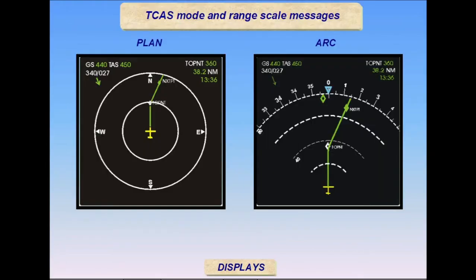When a TCAS message is present with the plan mode selected, a TCAS change mode message is displayed. It would be confusing to display relative bearing information in this north-up map presentation.